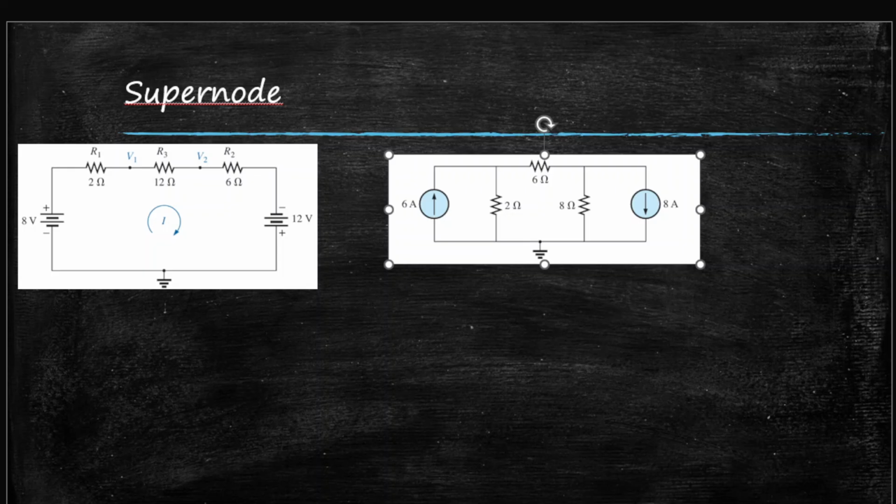So these two images are actually the same. Here this current source has just been converted to a voltage source. The numbers are not the same, obviously. Just the format and the arrangement of the circuit of the network is the same, just with source conversion. So this is in current source form, and this has just been converted to voltage sources. The rest are the same.